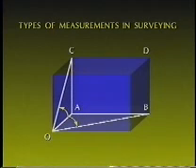Distance measurement is the basis of all surveying. In plane surveying, the distance between 2 points means the horizontal distance. If the points are at different elevations, the distance is the horizontal length between the two vertical lines of the points. The horizontal distance that relates to the slope distance OC is OA measured to the vertical line AC.